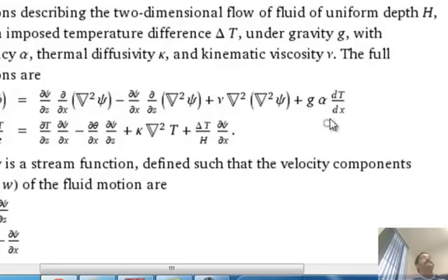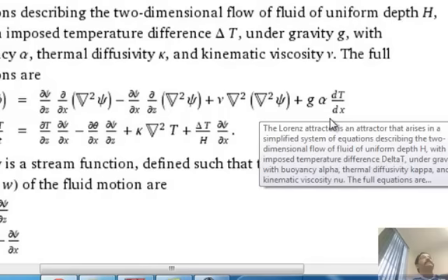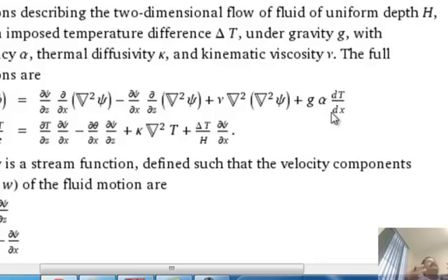Very good. That term stands for thermal buoyancy, a temperature gradient that causes density to change, that causes the flow to emerge. So he was studying the thermal instability in the atmosphere, rolling over, when you have a hot fluid at the bottom and cold fluid at the top. Cold fluid wants to descend, so there is a rollover of the atmosphere. So he's basically developing a model for that.